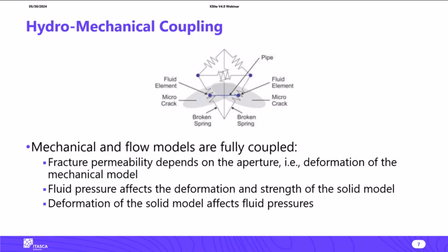Whenever a spring breaks or is intersected by a pre-existing joint, we assume there is a penny-shaped crack. That penny-shaped crack has a diameter which is roughly equal to the lattice resolution. In the calculation of the fluid flow, we use these penny-shaped cracks as reservoirs. We store fluid there and calculate the pore pressure changes and so on.